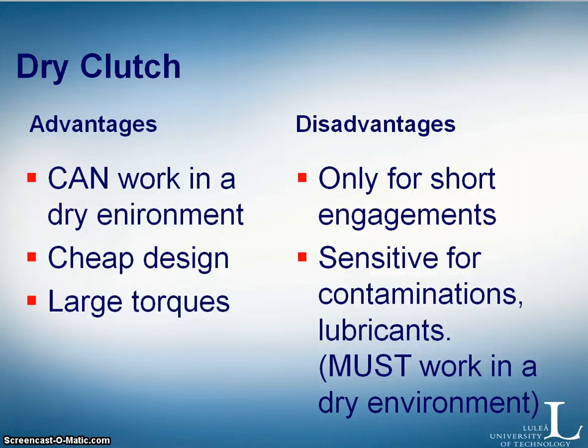So the advantages with the dry clutch are that it can work in a dry environment. It's cheap. You don't have to have any oil pumps or oil sumps or whatever, and it can handle large torques. The disadvantage with the dry clutch is that it can only be used for short engagement.